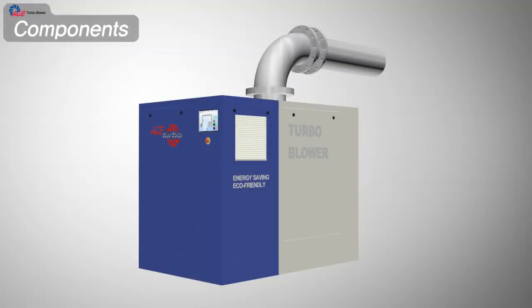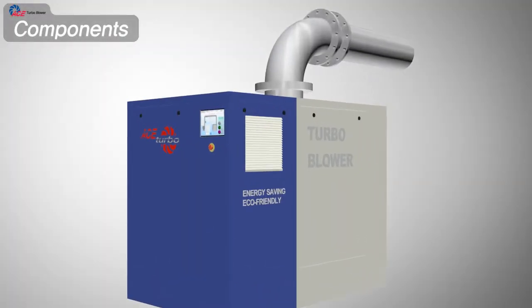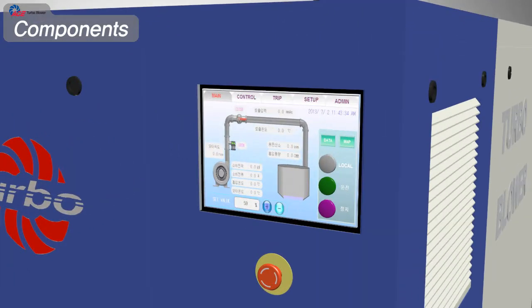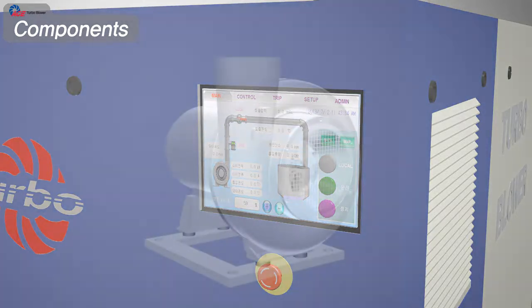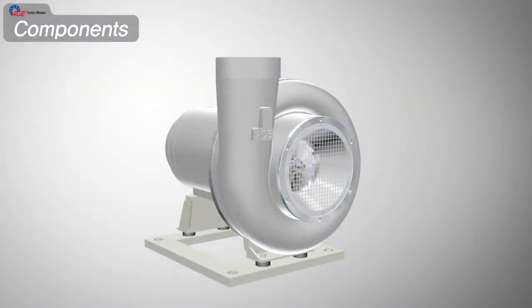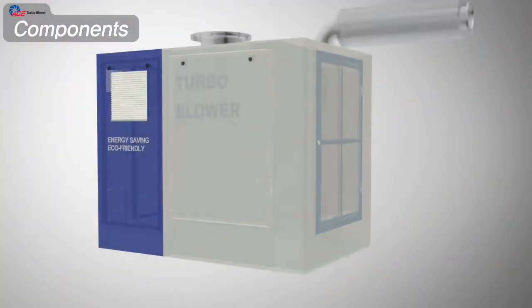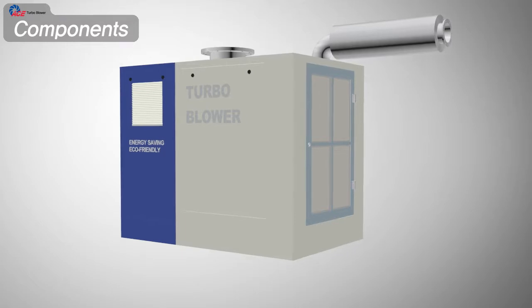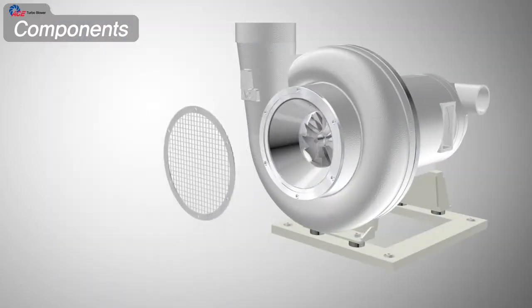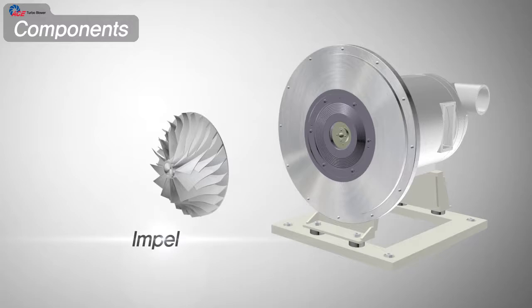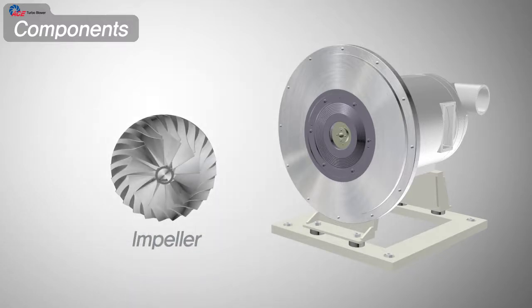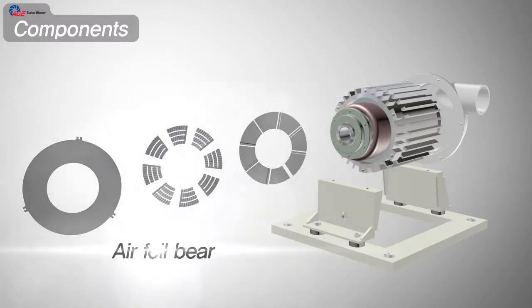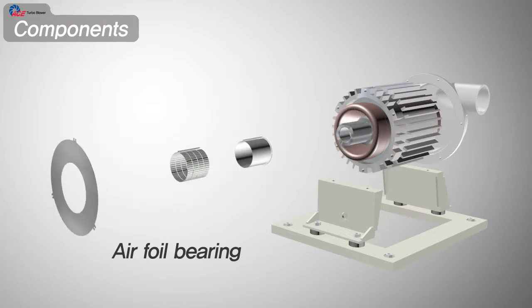The turbo blower mainly consists of 3 parts. First one is the control part, electric panel and inverter for controlling the blower. Second one is the air end part for compressing the working fluid, especially the air. Finally, the cabinet for inducing air and the sound insulation. The core component of turbo blower is the air end part, which consists of the impeller, thrust airfoil bearing and journal airfoil bearing.